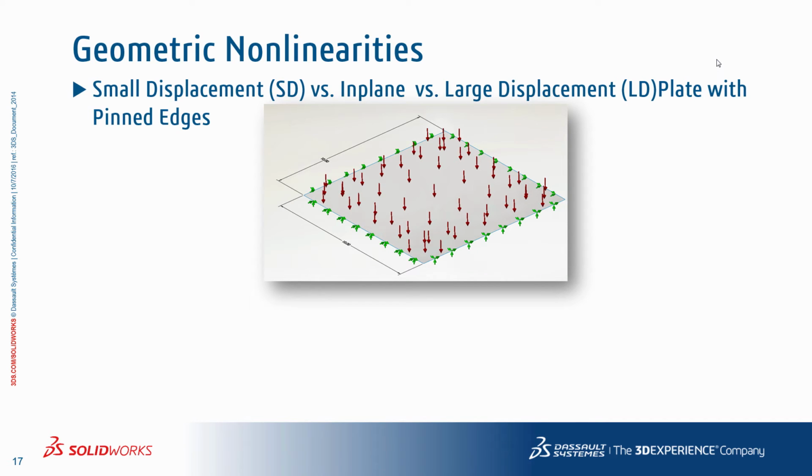Geometric nonlinearity is also labeled as a large displacement problem and is caused by tensile stress which results from larger displacements. The actual displacement in the model is not an indication of nonlinearity, nor is the tensile stress magnitude. The in-plane effect accounts for the stiffness of the structure and is actually a function of loads as well as deflections, which themselves are functions of load.